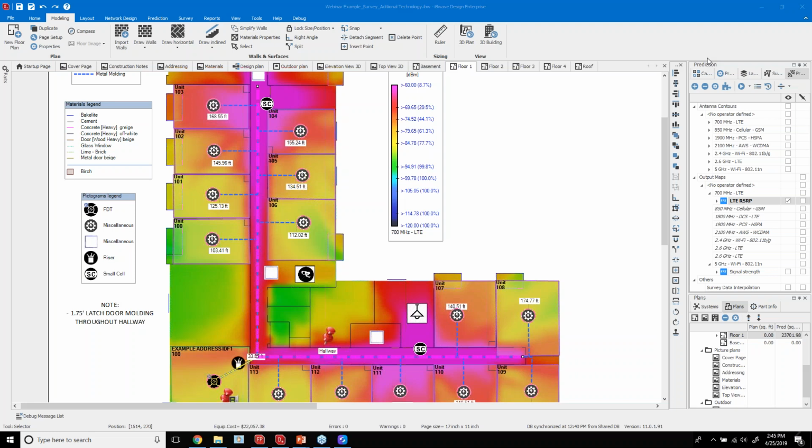If you're going with a multi-mode network or Ethernet network, you may need 2 fibers per unit for transmit and receive. So first thing to do is understand what electronics you intend to use for your network, and then that'll drive how much fiber you want to use. And then the fiber size in a distributed split network is a little tricky, but it's good to know 1x4 splitter, 1x8 splitter, and what that ratio impact is going to be to the cable downstream.